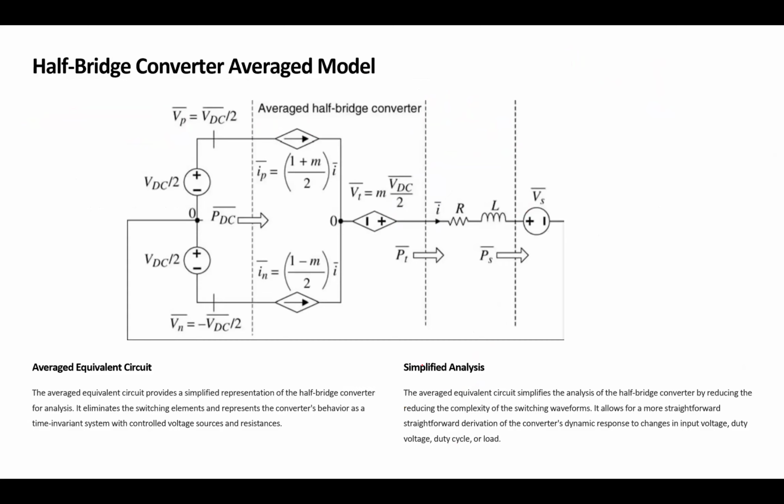Okay. Now, when we had those formulas, we could create our equivalent circuit based on the formulas we have as a function of the modulation index. This is the same graph that you saw before, but instead of the time-variant one, this is the average model, and we use the modulation index as the term that defines the average, which is 2D minus 1. Are we good? Same model, just the average model.